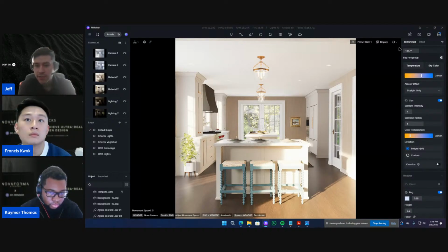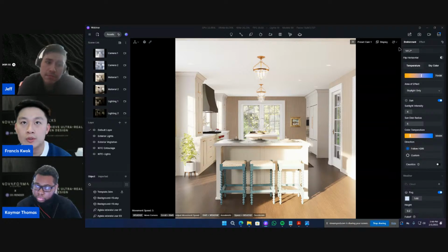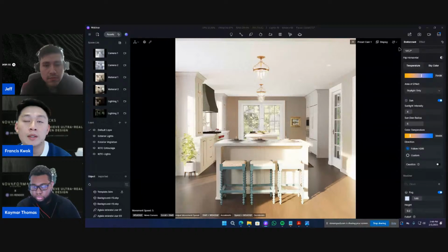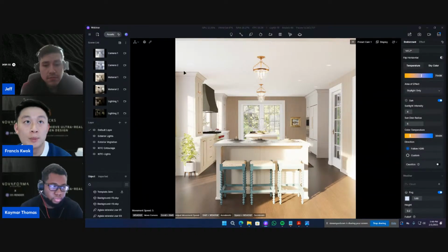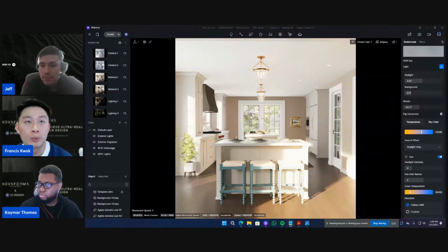Okay, nice. And maybe this is a question for Francis, but Pablo asked, how can you easily add those joints and cabinetry in Rhino? So in Rhino, you typically have a line. By utilizing a line in terms of details, whether you receive it from an interior designer or you're the one doing it, you could use the sweep tool, which basically sweeps and creates that detail that wraps around a corner, whether it's in the pantry, on a cabinet, or if you want to do a base or top molding.